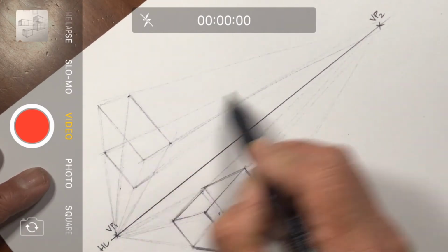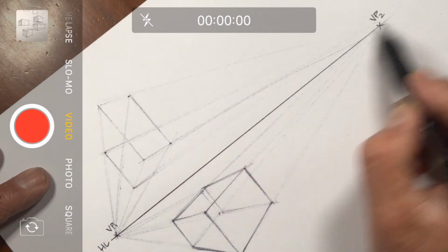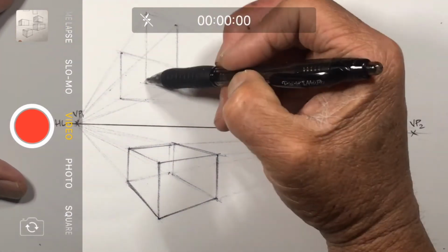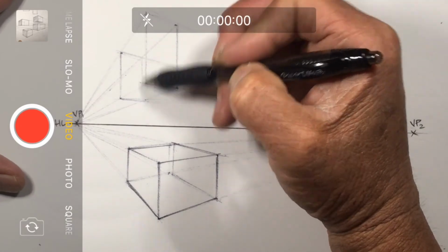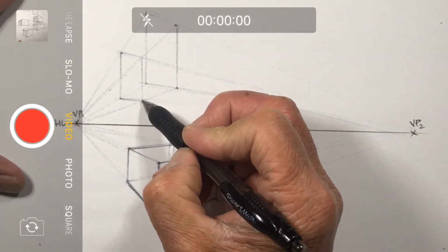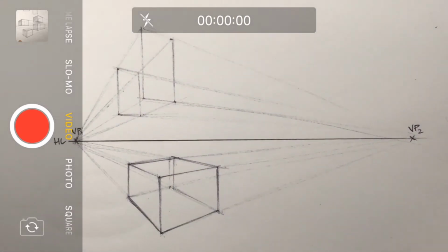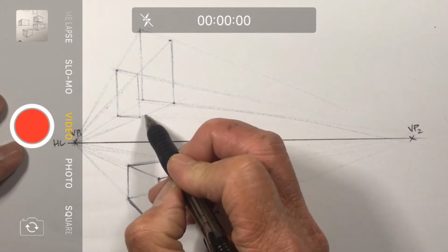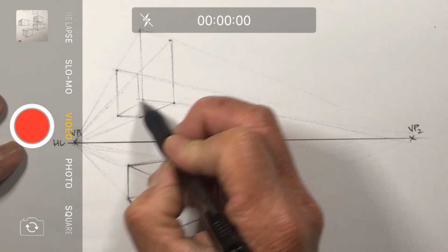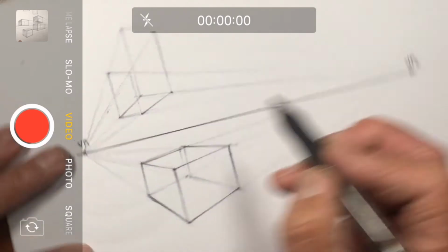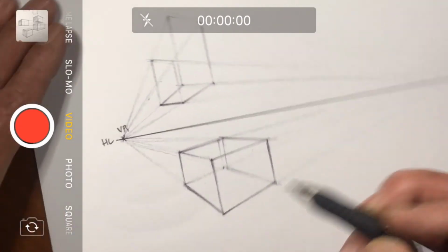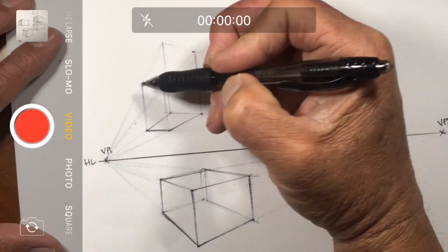And that's the key, I think, is to really work out, and it starts off with the pen that you choose, pressure, so that you can just have enough ink to see the construction line. And that construction line really is just there for you to see. It's not for anyone else. Sometimes I draw a little heavier because it doesn't show up on the camera. Of course, then we use heavier line weight to construct the object, which is a box here, as a solid object.